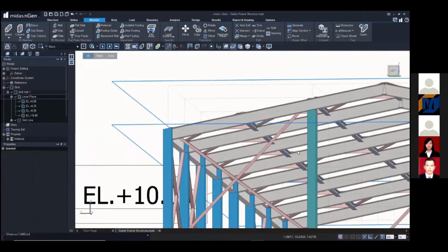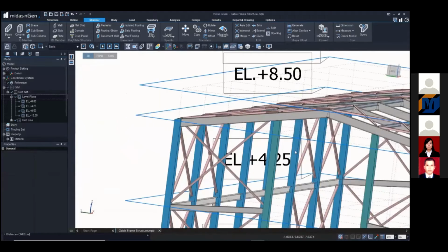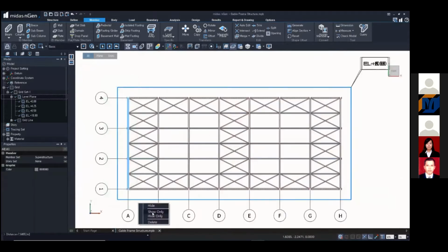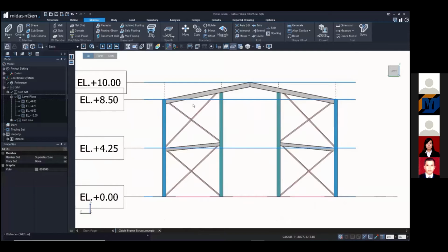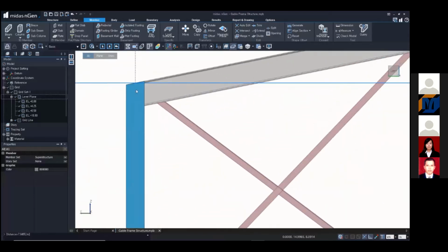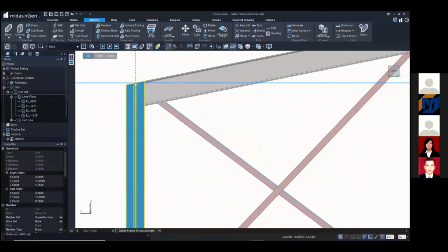Let's show only a few members. After selection, right click and click show only. At this time, confirm the end point of the brace member. When the member is clicked and end offset is cut back, the shape is connected to the lower part of the flange of the gutter. However, the center point for the analysis is in the form of the single line.